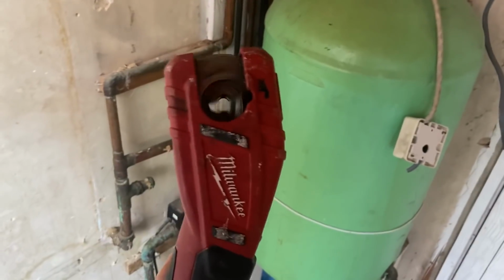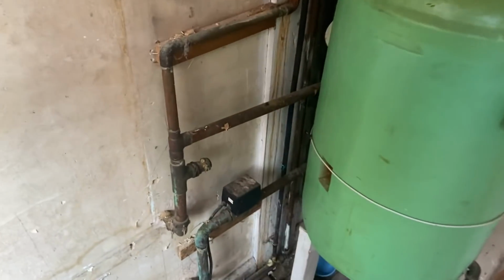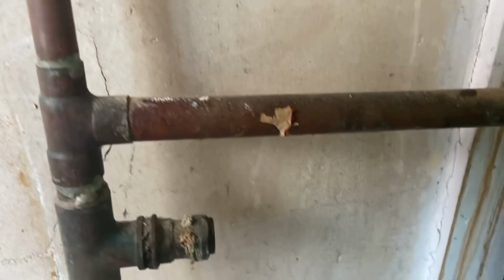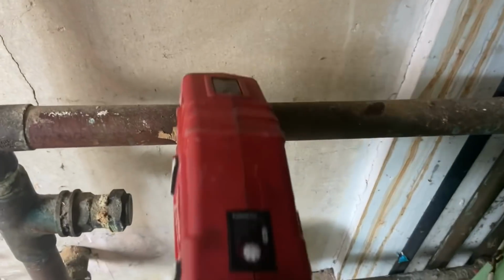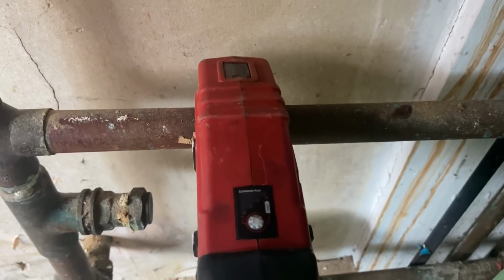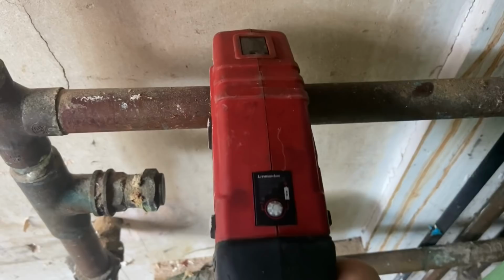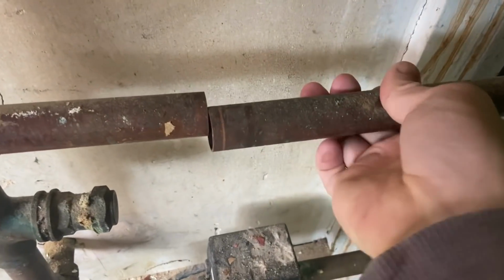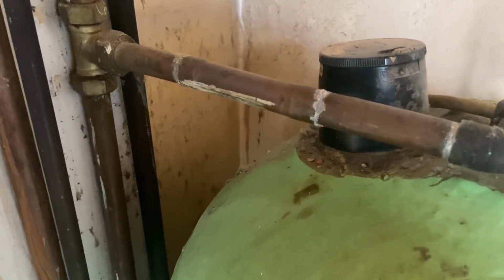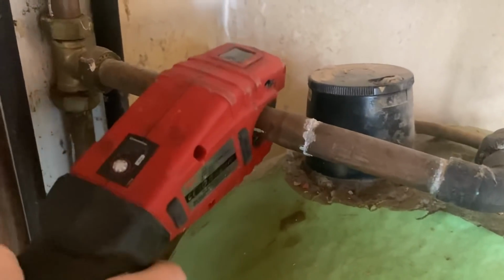If you remember the live video I did on Monday, this is that job, full central heating, big rip out, and that's when this becomes really handy, because I've got a lot of copper to strip out of this job. So 28mm primary, no problem. This is going to be a pretty boring video because you're just going to be watching me cut pipe, but that's the 28mm cut. Reset it, move on to 22mm, no adjustment, just reset the cutter and pop it on.